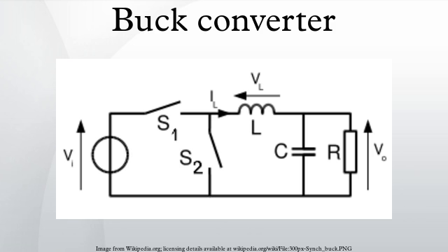As mentioned at the beginning of this section, the converter operates in discontinuous mode when low current is drawn by the load, and in continuous mode at higher load current levels. The limit between discontinuous and continuous modes is reached when the inductor current falls to zero exactly at the end of the commutation cycle. Using the notations of Figure 5, this corresponds to the following. Therefore, the output current at the limit between discontinuous and continuous modes is as follows. Substituting ILmax by its value.